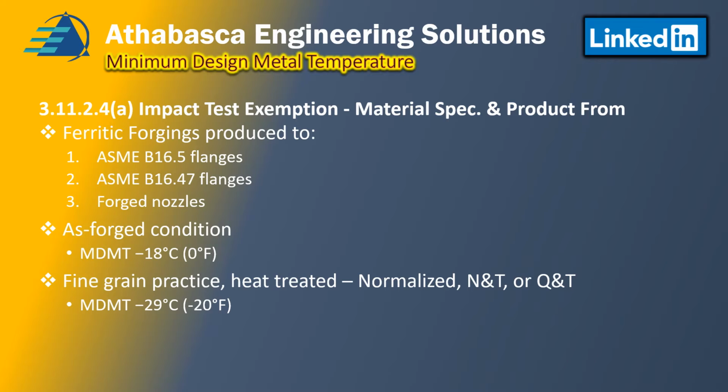If you do heat treating and you can show that it's done to a fine-grained practice, and we talked earlier about SA20, which means it's heat treated, normalized and tempered or quenched and tempered, then you get an instant credit down to minus 29 degrees centigrade or minus 20. And this is identical to Section 8, Division 1, UCS 66C.